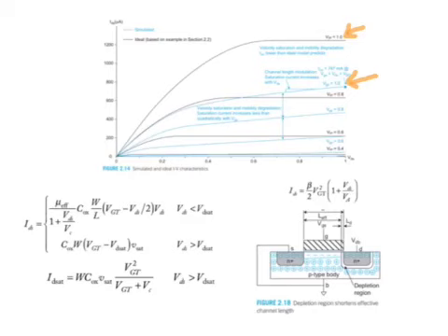You can see that the magnitude of the current is significantly decreased as such. That's the first step. And second, you'd observe that the point where the transistor transitions from linear to saturation, meaning the formation of the channel pinch and then pinch off happens, this is now a linear function.